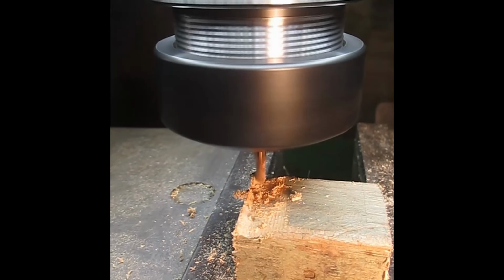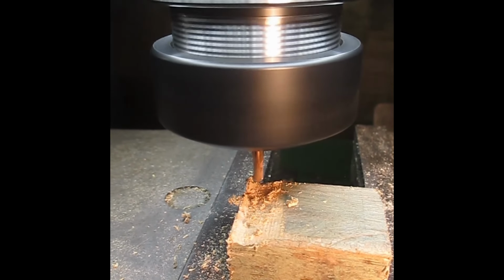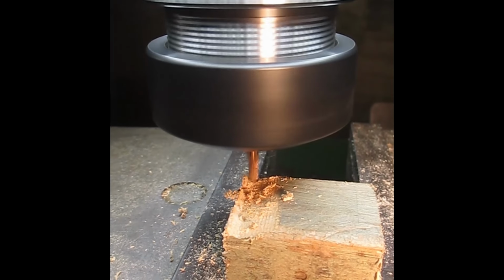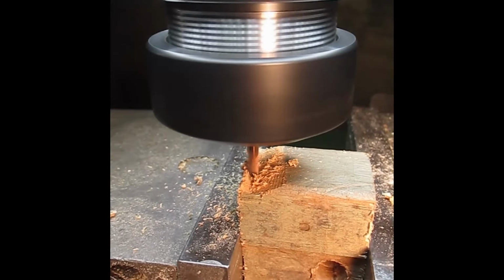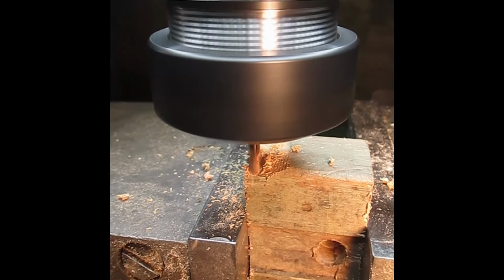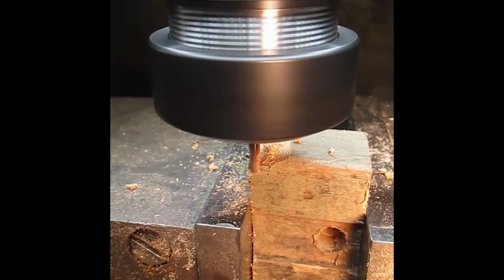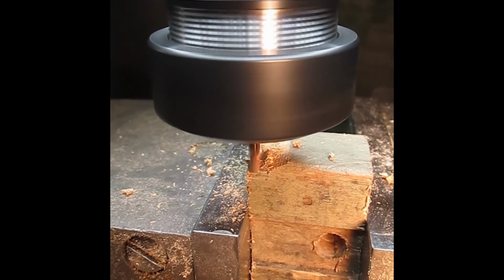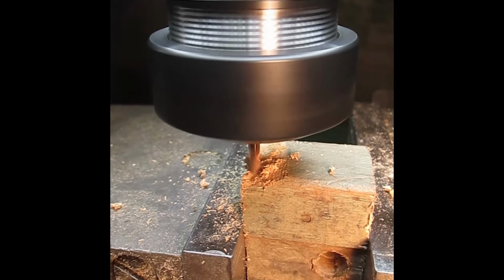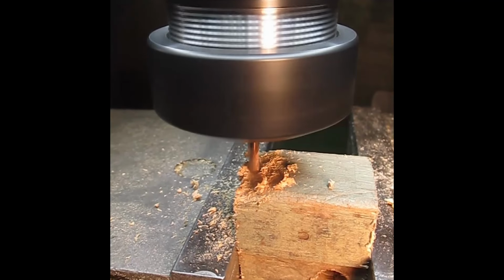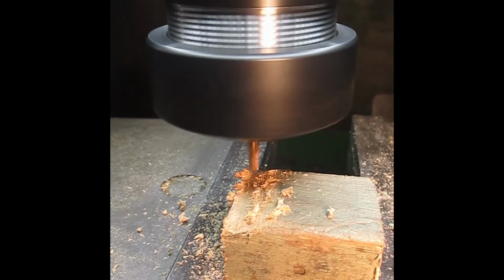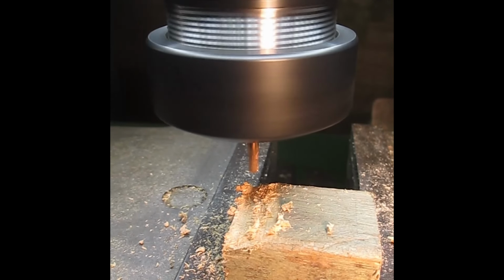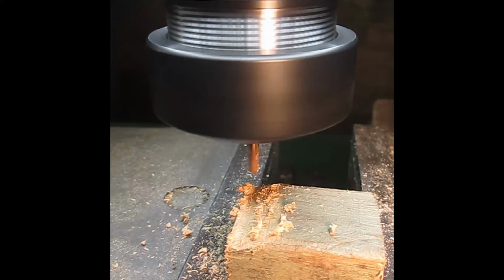The slotting command is actually cutting back and forth in the x direction, and I'm using it because if I didn't, the depth of the plunge that it would make by just following down that slope would mean I'd start machining, or trying to machine, with the actual shank of the cutter. So I select a suitable pecking depth on the slot so that I'm not taking too big a bite with the cutter on each pass.